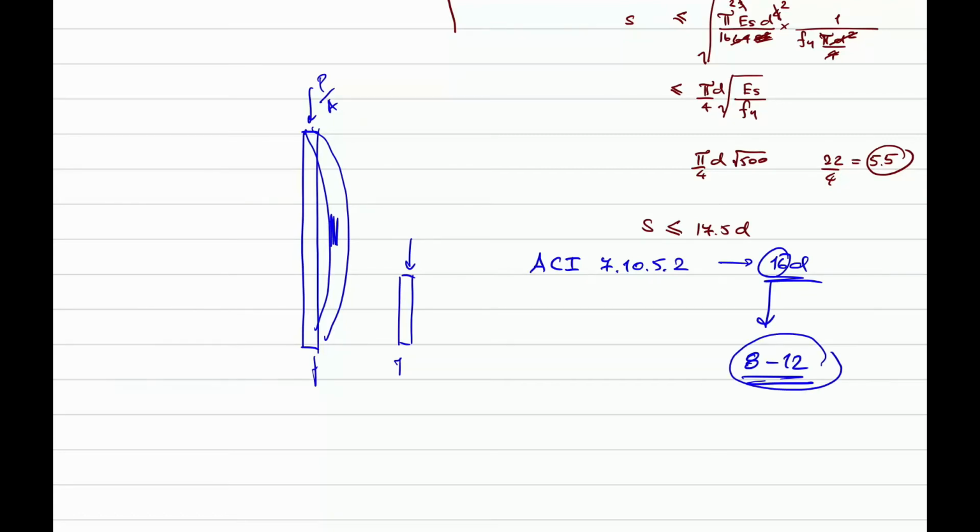Well, to make it clear and to make sure, read the commentary. But from the physical point of view, I think the rationale is that the slender column will be subjected to this high compressive stress. This could also apply to the beam case, where you have the high strain the code mentioned, for example the plastic hinge zone.